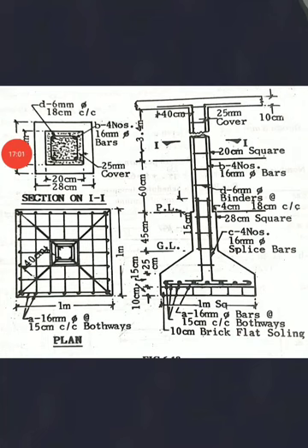See, the splice bar is coming like this and it is going to be bent like this. Now that bend here will be like this, right? 4 splice bars, you can see this, right? And here it has given 40 centimeter. You might be asking from where I have taken that 40 centimeter bend. It is given in the figure, right? So that's how you are supposed to take these splice bars, with that 40 centimeter L bend.